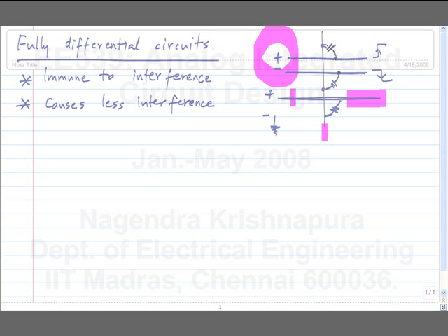Now, one more advantageous aspect is that we operate in a supply limited environment, okay. So, all our swings are limited somehow by the supply. We have seen that in every case the swing limit will be VDD minus something. If the circuit is good for swing, that something will be small. So the signal swing will be close to VDD. If this is 0 volts and this is VDD, perhaps you can swing up to here. Okay.